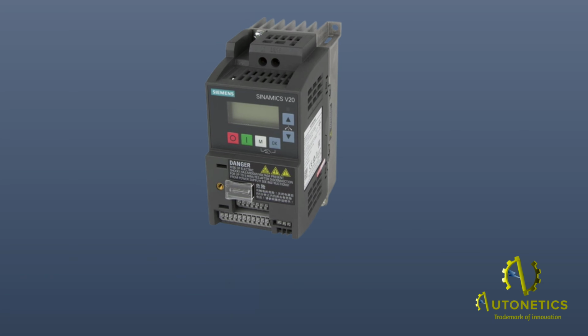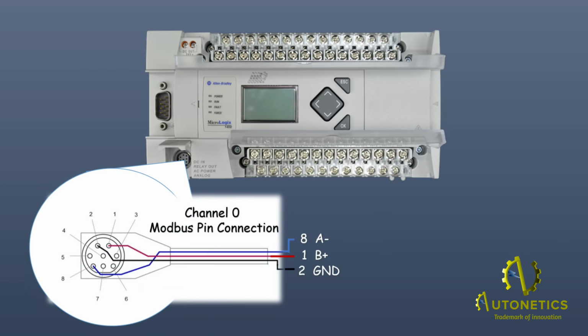Okay. Let's first look at SINAMICS V20 VFD side. SINAMICS V20 VFD supports the USS Modbus protocol. At pins 6 and 7, you get Modbus port P plus and N, respectively. Also, at MICROLOGIX 1400 PLC side, the Modbus port is available on channel 0. Let's configure Modbus communication on both sides.